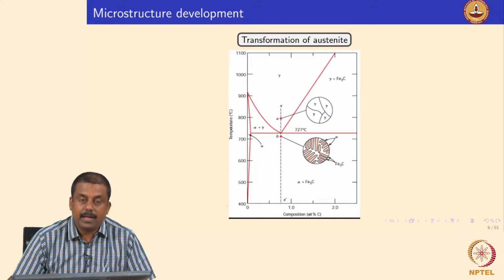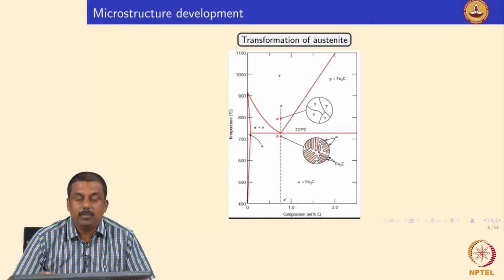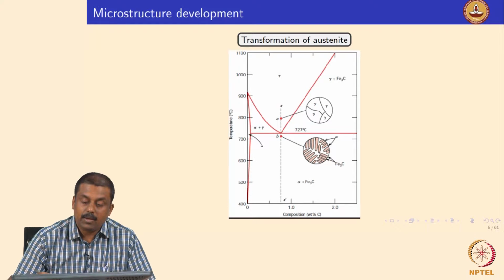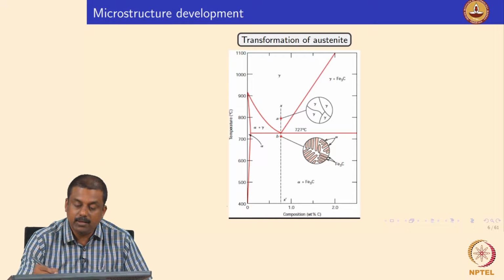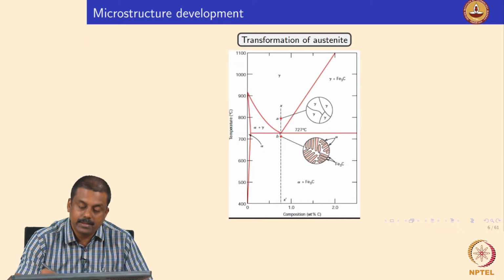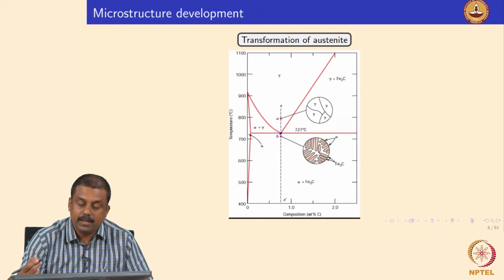first what is the forming mechanism of pearlite from the austenite when you are cooling down at various compositions, and we will move on to the effect of alloying elements on the transformations, and subsequently we will go to see the effect of cooling rates, or the time factor, in these transformations. So, I already explained that the 0.76% carbon is your eutectoid carbon concentration.